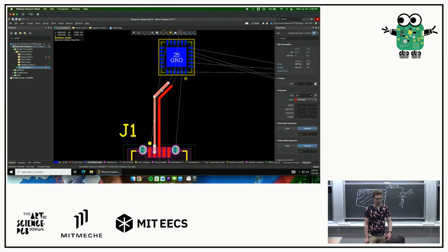And then it's just the resistance of the via, which they can account for by testing the via. You can get specs on what impedance you want your via to be, and once you have that, you can account for that resistance in whatever calculation you're doing to measure your signal, and then your ground plane effectively has negligible resistance. That makes sense. Cool.